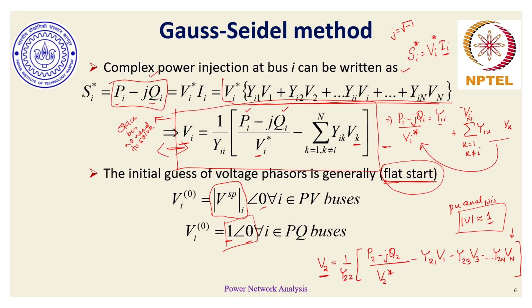So for the kth step, or for the first step, if I associate the initial choices with a superscript, let's say 0, then V1 superscript 0 doesn't make sense, because V1 refers to the slack bus. Its voltage would always remain constant. So V1 doesn't need any subscript or superscript like 0 or 1 indicating the recursion number. V1 would remain fixed as it is chosen as the slack bus. We know what V3 0 and Vn 0 are, which are essentially these initial choices that I have marked.